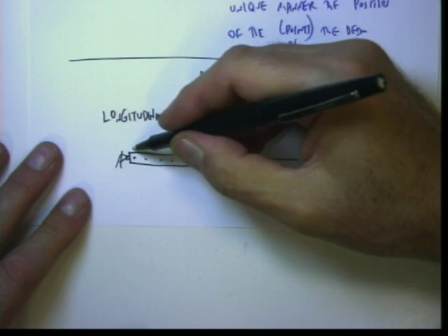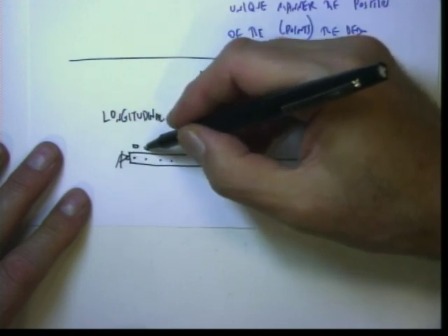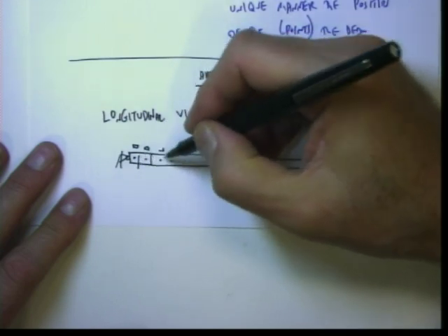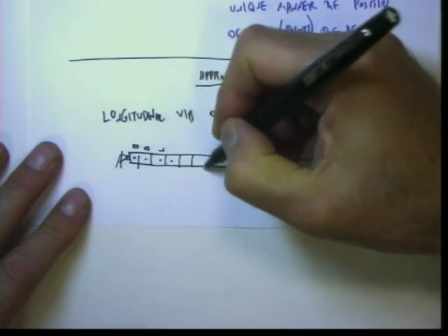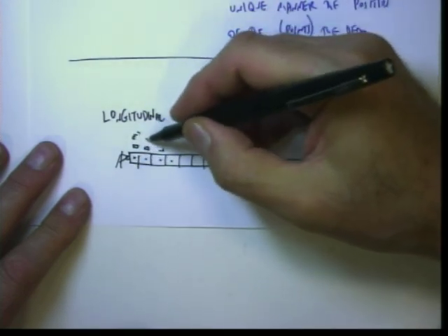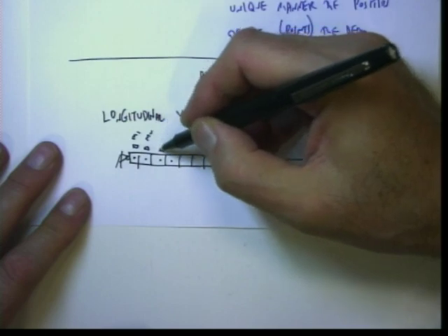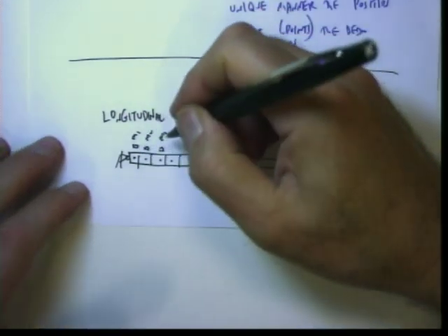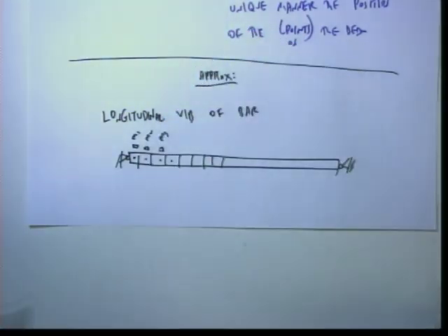So this is actually equivalent to having here 1 degree of freedom, and here 1 degree of freedom, this mass. So imagine I'm cutting this and I'm lumping the masses. So this mass is here, M1. This mass is here, M2. This mass is here, M3, etc. And then there should be some springs attached.